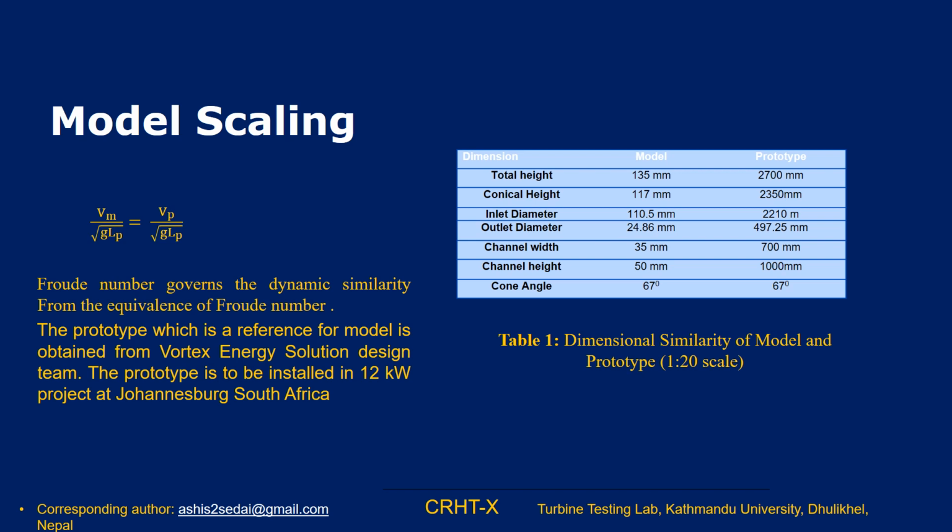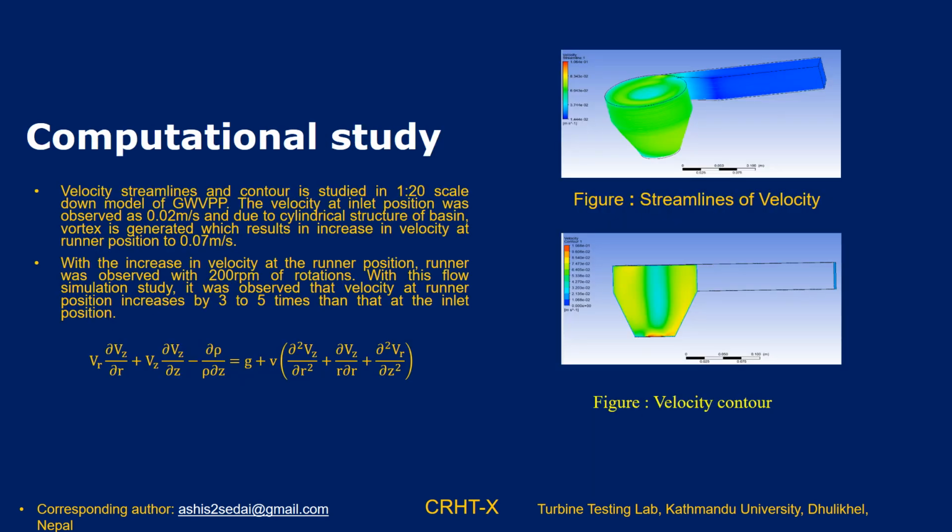The table represents the dimensions of the model and the prototype that we did the investigation on. After scaling was done, we studied the computational study of the model. For that, we made a fluid domain in a solid box. Then we imported it to ANSYS CFX, and then we discretized it to generate small units by hex dominant meshing with free face type set to all quadrilaterals to produce a uniform meshing.